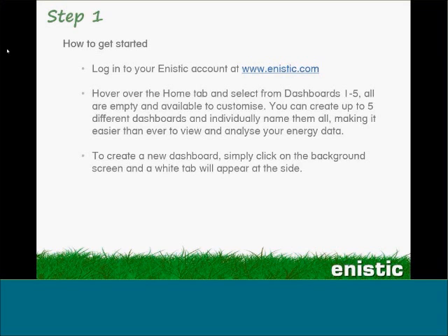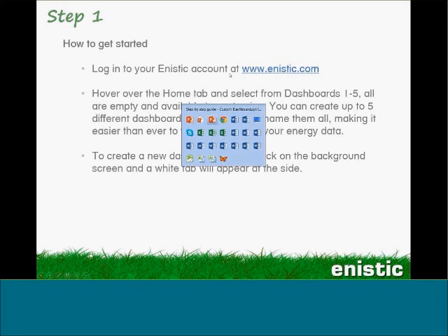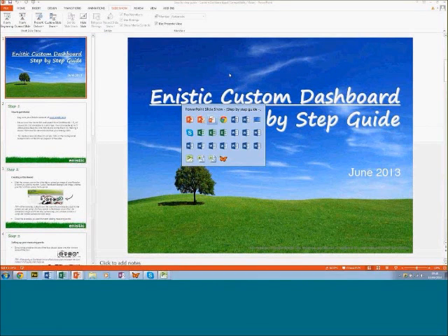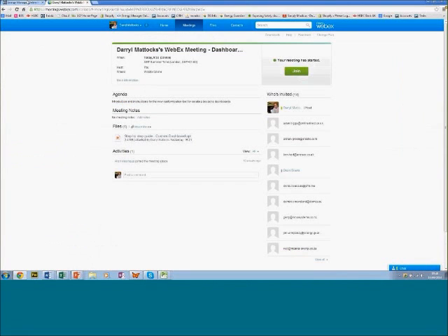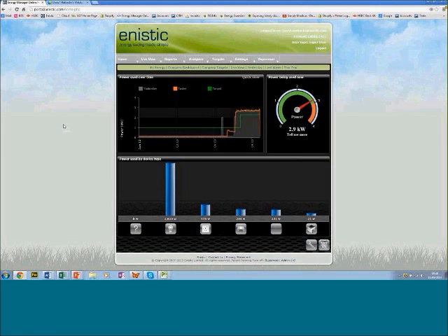If we go here, for example, this is the standard dashboard of Energy Manager Pro, and this is our office. This is a real life office. You can see that someone came in this morning at 6:30 briefly, probably one of the engineers picked something up, and then someone came in at 7:30, probably Paul. It wasn't me today. We're running 2.9 kilowatts of power at the moment in this office, largely, as you can see down in this bottom area, on the lighting.